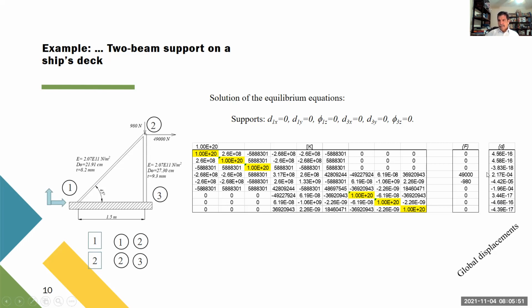And then these are the displacements that we need for this joint. It moves to the right, moves downwards, makes sense. This rotates in the negative direction. If this is the global reference system, positive is counterclockwise. In this case, we obtain a negative, that means that it rotates in the positive sense. It makes sense.